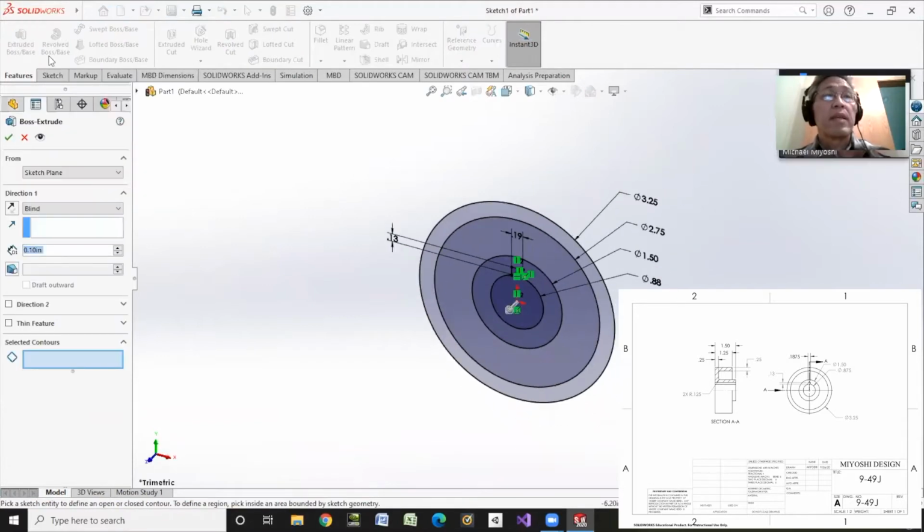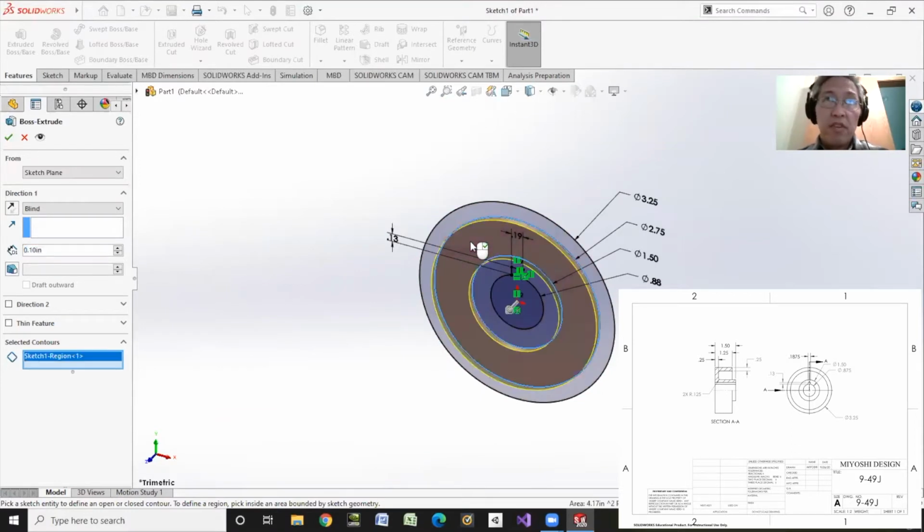Now, this one I'm going to do a little different. I'm going to go ahead and extrude different parts. So I'm going to extrude, let's not extrude the outside yet. I'm going to extrude this part here, and it's fairly short. Just extrude it 0.25, quarter of an inch, and then I'll hit OK.